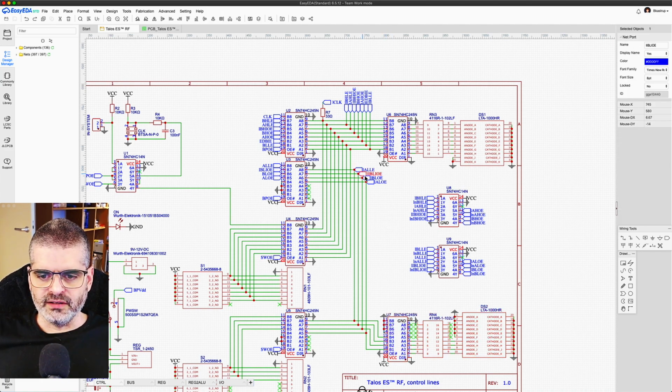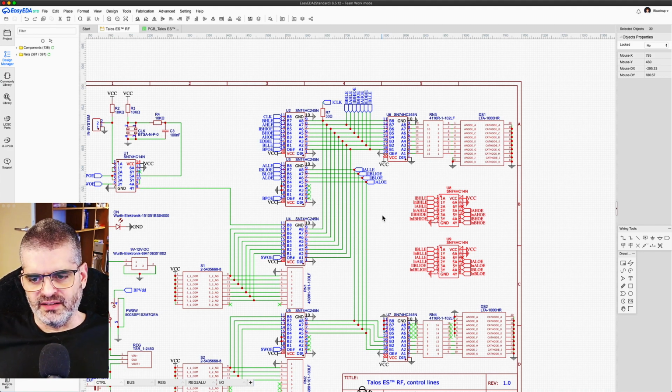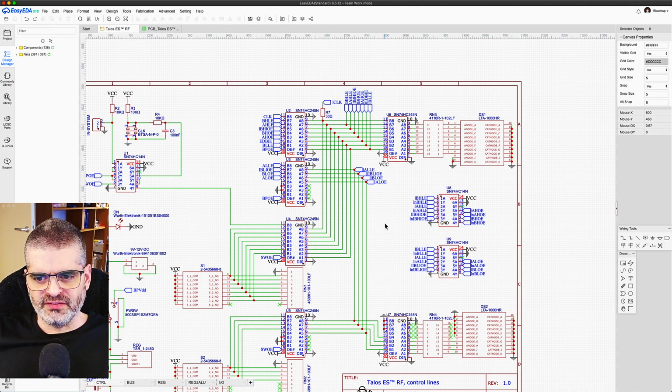Now the selected signal then goes through the inverters, because in the control word we have positive logic. Buffer enable is active high, because if it were active low, when we reset the computer and the pipeline registers go to 0, all buffers will be enabled and we'll have bus conflicts. So in the control word we have to have positive logic, but we know that the chips require negative logic.